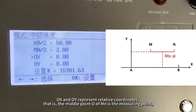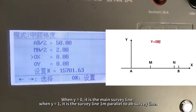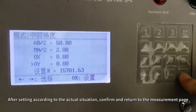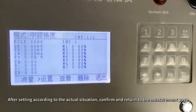Ox and Oy represent relative coordinates, that is, the middle point O of MN is the measuring point. AB is the x-axis of the coordinate axis, and the y-axis data is the parallel distance between MN and AB survey line. When y equals 0, it is the main survey line. When y equals 1, it is the survey line 1m parallel to AB survey line. After setting according to the actual situation, confirm and return to the measurement page.